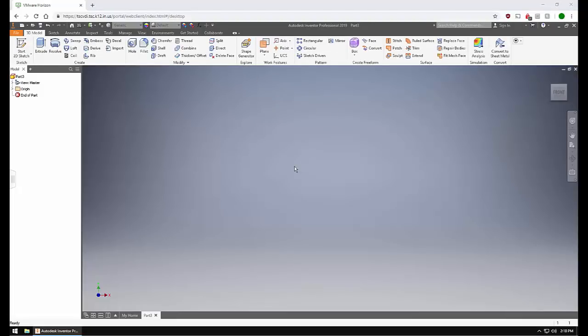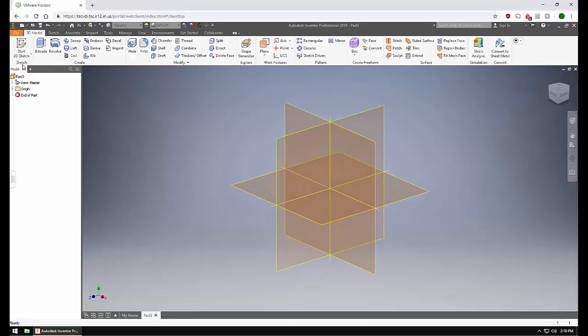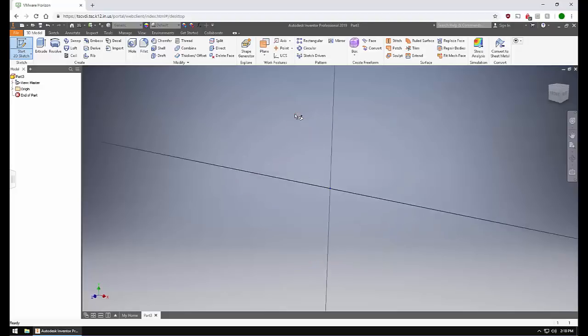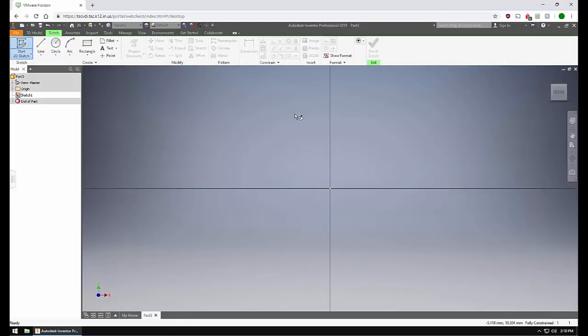We are now going to go over how to edit a part. In the 3D Model tab, select Start 2D Sketch. Then select the XY plane. From this point, you may start drawing. I will go over several drawing tools that we will use.